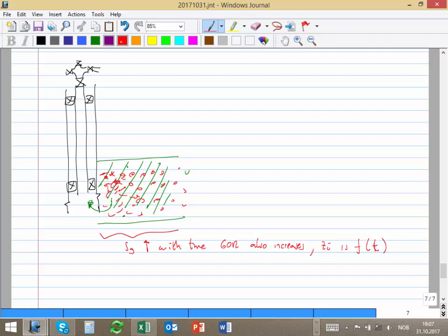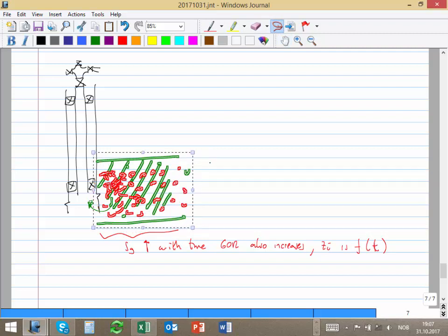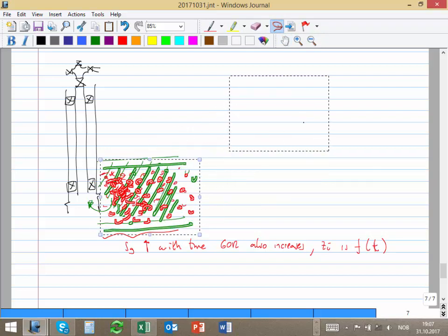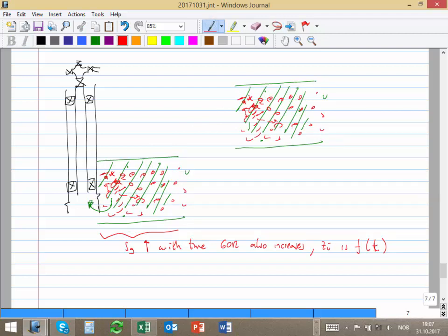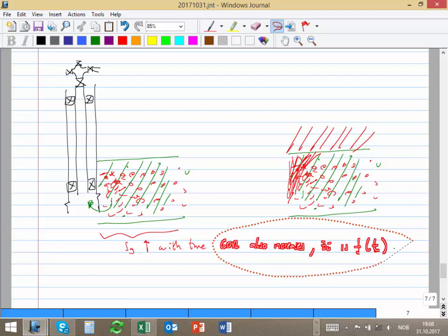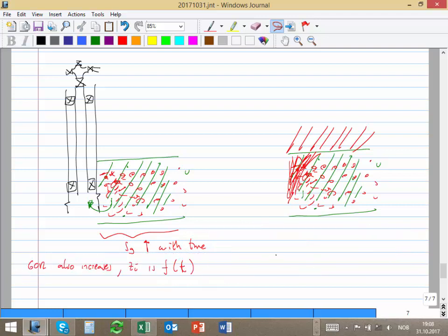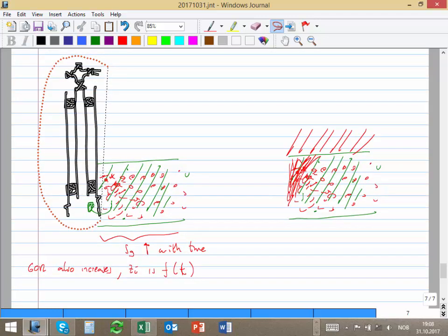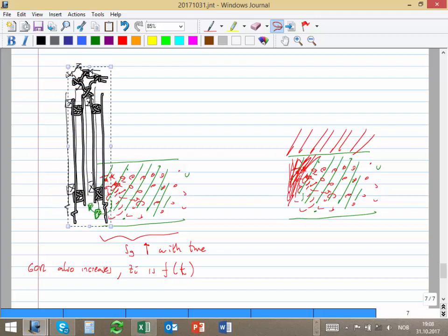And also the same thing if you have, for example, coning. Let's copy exactly the same diagram. If you have a gas cap here, and then you have coning, gas from the gas cap starts entering into the well. Let's copy the well so it won't be alone.